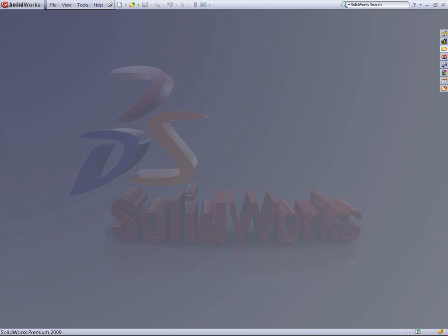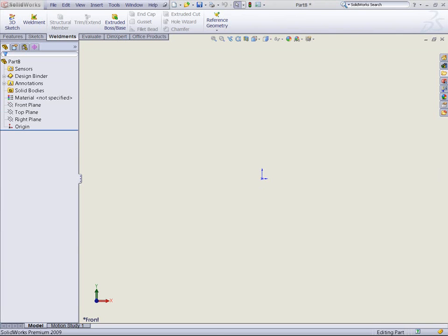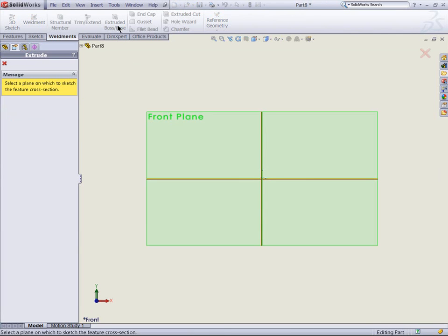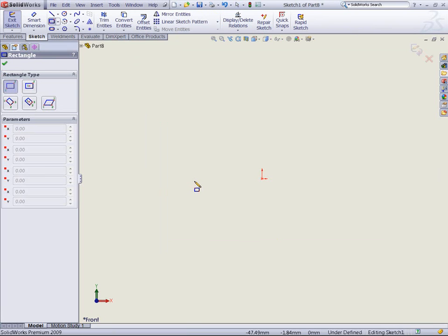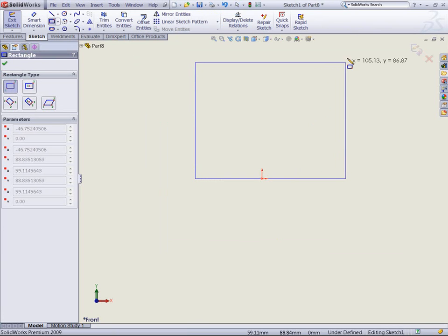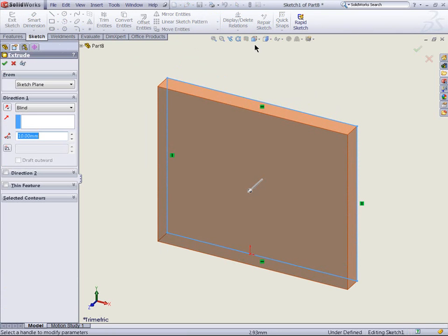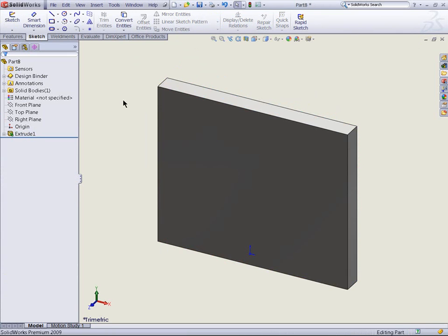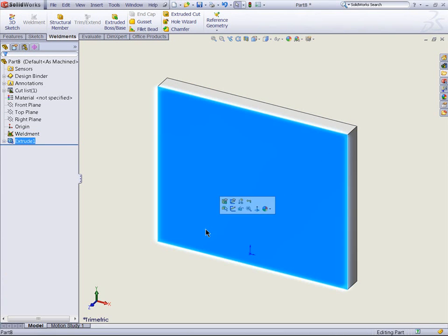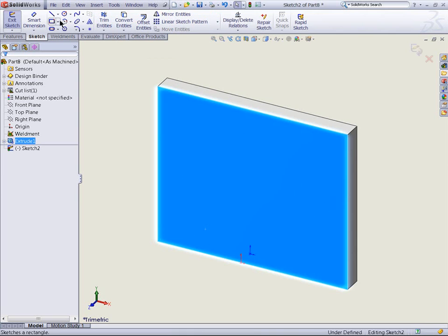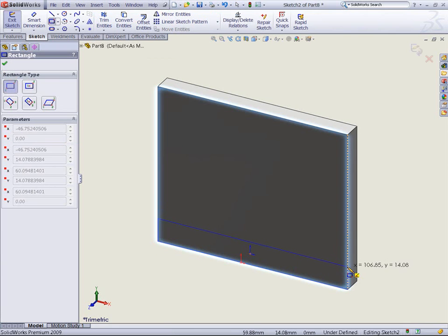One last tip on non-structural members. I can still generate a weldment without using structural members. I can go ahead and throw an extrude and draw up a plate. And when I invoke the weldment feature, when I go to apply my secondary extrude, you'll notice that the merge results checkbox will be unchecked.